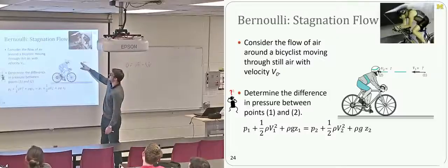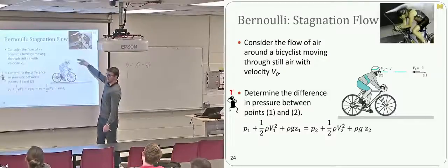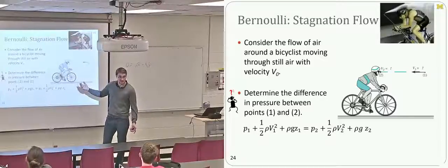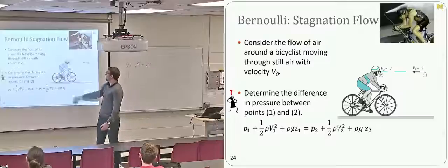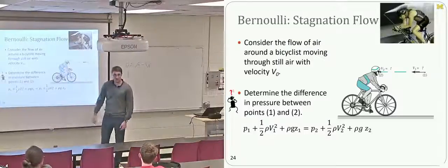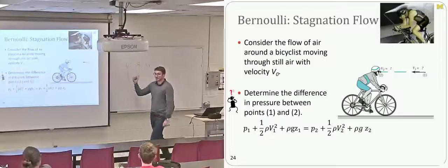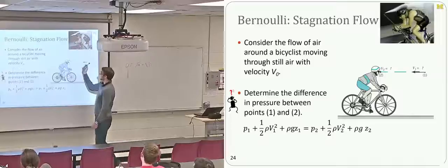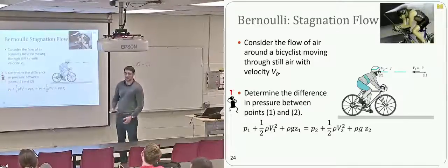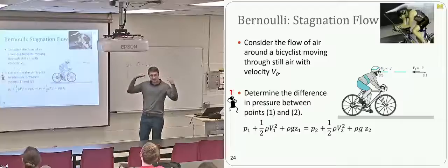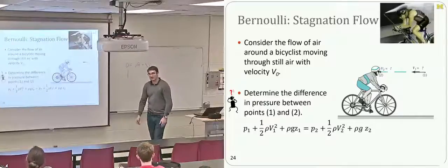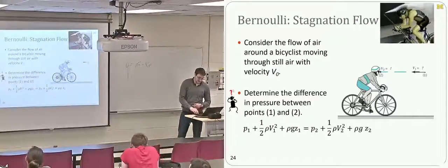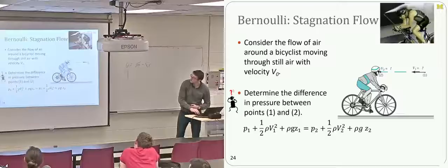So we could say that the velocity here is 0, but as he rides past, the velocity here is going to get perturbed and go all over the place, and then go back to 0. So that means it's an unsteady coordinate system, right? However, if we put the coordinate system on his nose, and simply say that it's advancing with him at speed V naught, then that coordinate system doesn't see any unsteadiness. It's simply advancing with the constant inflow. It's always got a stagnation point on its face at the same point in the coordinate frame.